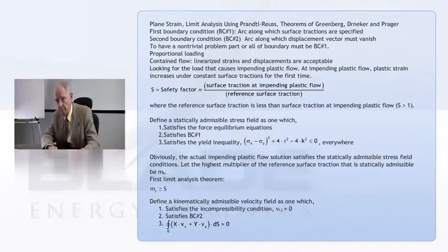And then everywhere in the stress field, we have to satisfy the Mises inequality to say it doesn't yield. So what we've done is we've found a stress field that's okay as far as these equilibrium equations go. It's okay as far as the stress boundary conditions go. And the stresses in this field don't exceed the yield point.